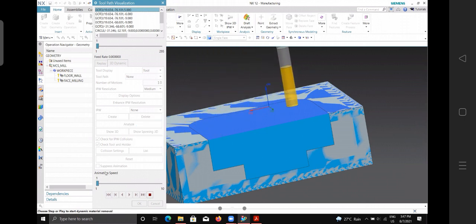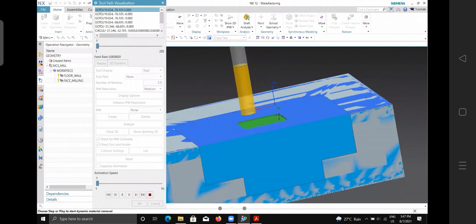So this unnecessarily wastes the movement of the tool, or this just increases the machining time, and it will not be efficient. After the fourth or fifth pass, it starts cutting. That is why I am giving the blank distance as 40. So this is how you can understand what to give the blank distance.